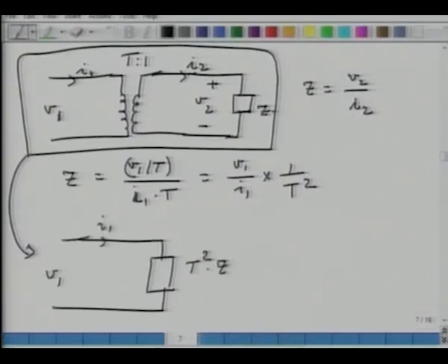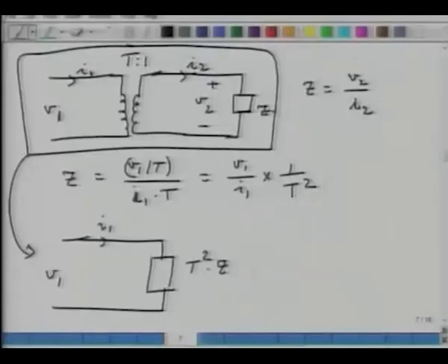Is that clear? Whenever there is a transformation happening from electrical to mechanical, it is important to figure out the ratio. For instance, in a coil which moves back and forth, force equals BIL, from the laws of electromechanics. So the turn ratio there is BL.